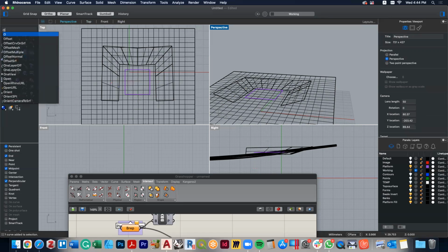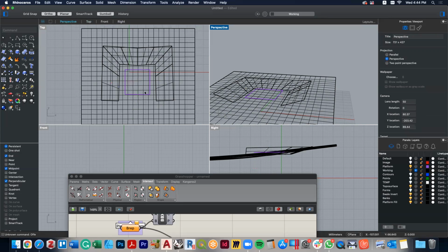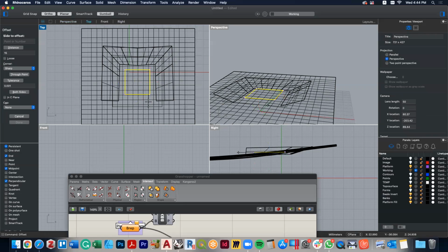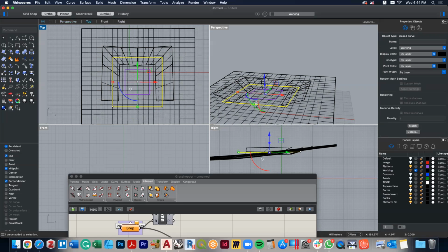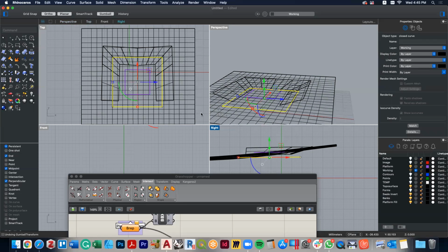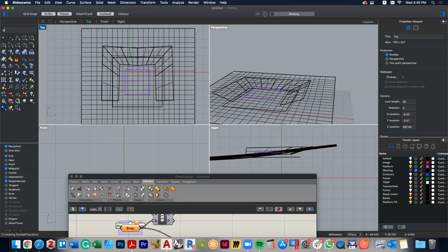I'm going to offset this again, and we're going to offset it this time 15. Okay, that's right. But now we're also going to move it 5. Whoops, oh no, that's gone up. -5. Okay, now let's do again our edge surf. In fact, loft is more reliable.